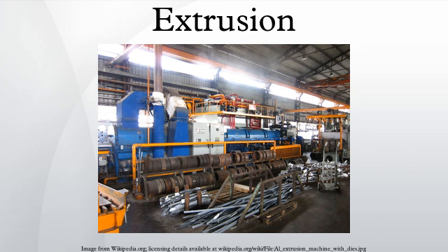This ultimately allows for faster speeds, higher reduction ratios, and lower billet temperatures. Usually the ductility of the material increases when high pressures are applied. An even flow of material. Large billets and large cross-sections can be extruded. No billet residue is left on the container walls.